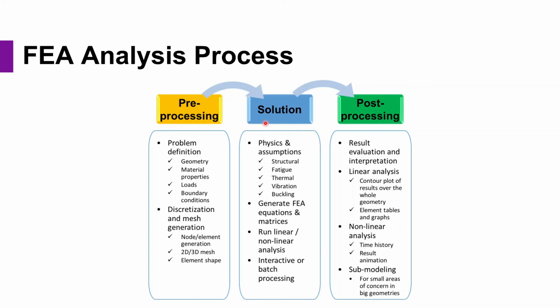And once you have everything in here, you'll go to the next stage, which we call the solution stage. Within the solution stage, I have to tell the software what kind of basic analysis you want to do, whether it's structural, fatigue, thermal, vibration, buckling, and so on. We already discussed that. So I have to tell the software which of these I want to use. Based on that, I will decide what kind of solver, what kind of mathematical equation the software needs to work with. And you can see that the equation and matrix will be defined. I have to tell the software whether I want a linear or non-linear analysis, because again, a different kind of solver and different formulations and mathematical equations are required.